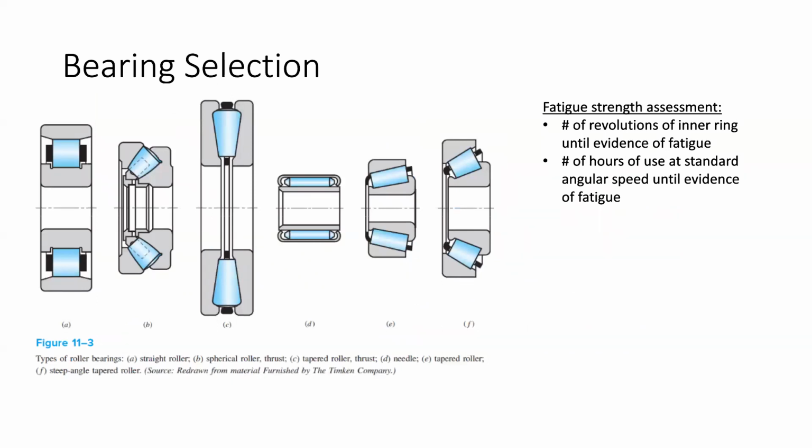Okay, so we've talked a little bit about material selection from the standpoint of several different properties. These properties manifest in interesting ways in very common types of systems. For any of you familiar with bearings, there are several different types, right? You have a straight roller, which is pretty common, where there are cylindrical elements which separate an inner and outer ring. In general, when you see a bearing, it's going to be constructed of some kind of inner ring with a really hard material, since that's what interfaces with your part, and an outer ring. It's typically very precisely machined because you care about things like how much play the bearing has and how stiff it is.